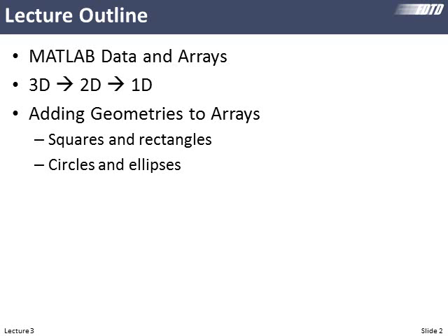So first we'll talk about MATLAB data and arrays, how to initialize them. And in this class, we, for the most part, will not be doing three-dimensional modeling. We'll talk about it off and on. So we need to understand a three-dimensional model, because we live in a three-dimensional world, everything really is three-dimensional. What does it mean when we talk about a two-dimensional and one-dimensional model? And in fact, what you'll see is even if we're doing a one-dimensional finite difference time domain code, in fact, we're modeling something that is three-dimensional. And so to understand that relation, I think, is very important. After that, the meat of the lecture is really discussing how we add the geometry of what you want to model to the array so that we can model it.